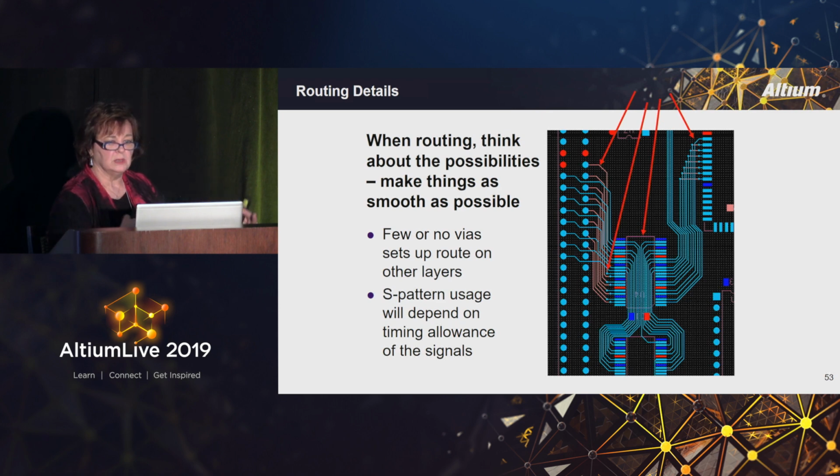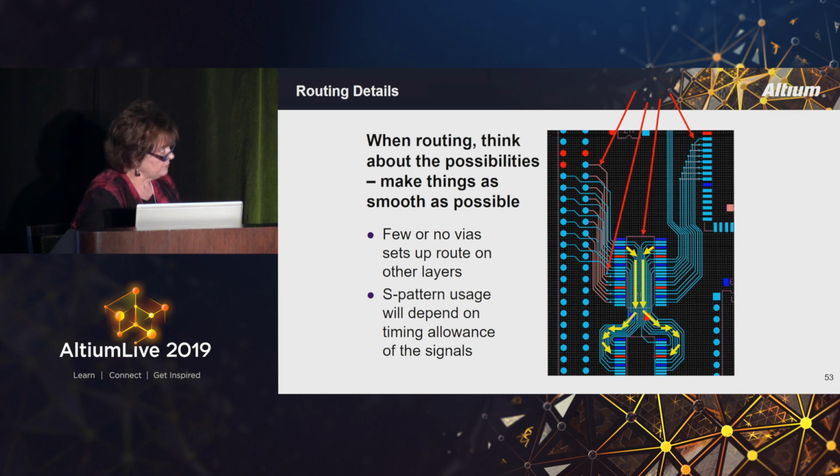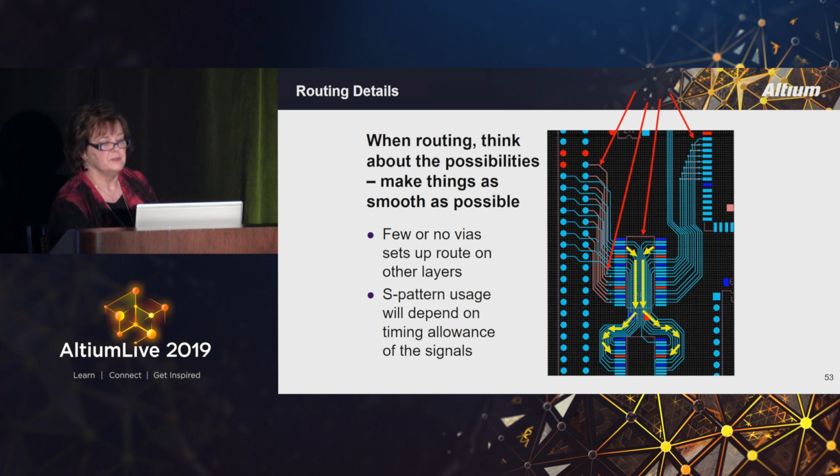And so if you look at the way that these signals are flowing and try to figure out if you can route them on one layer, then it's very beneficial for the signals. And it's very beneficial for other routing on other layers.